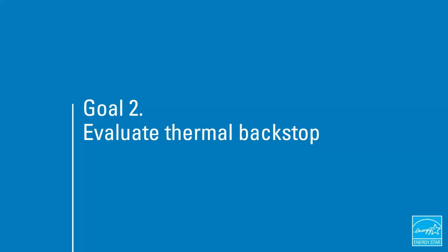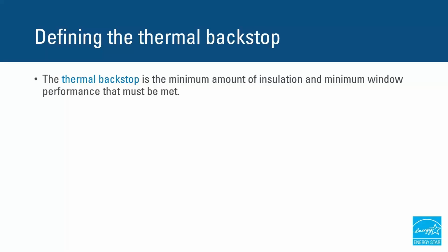Okay, so let's move on to our second goal, which was to evaluate the thermal backstop associated with this new version. As a refresher, the thermal backstop is the minimum amount of insulation and the minimum window performance that must be met for a home to be certified.